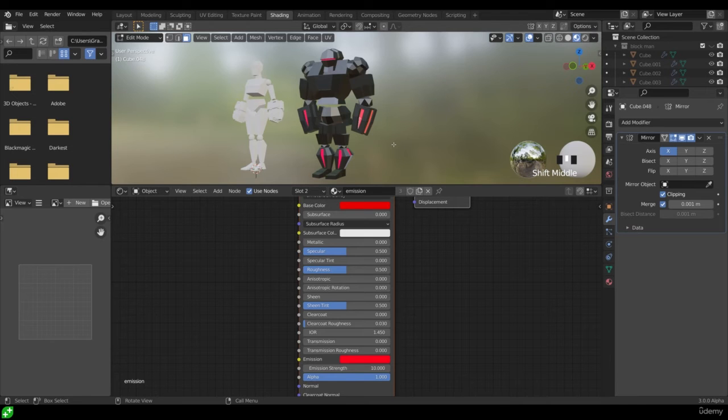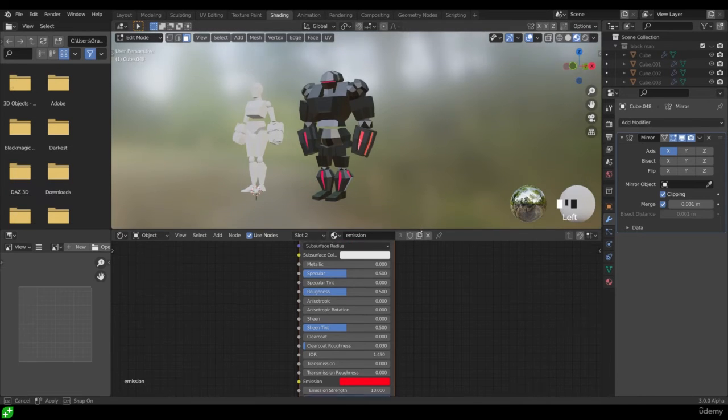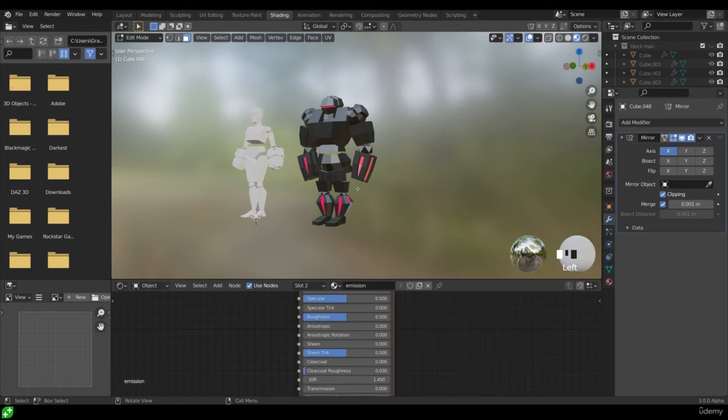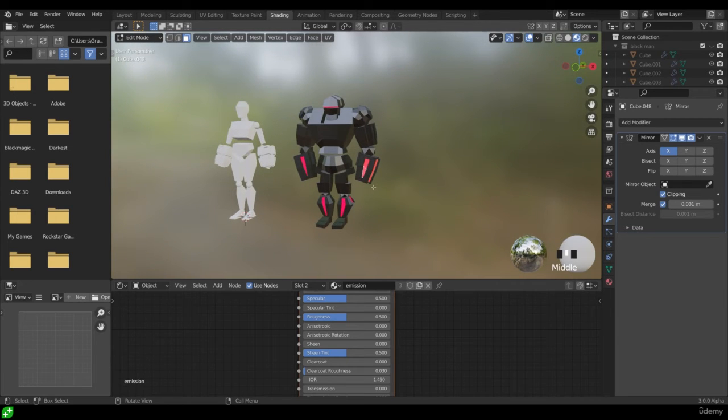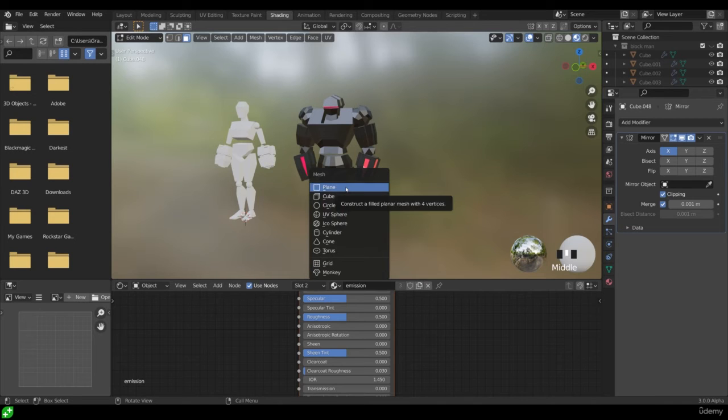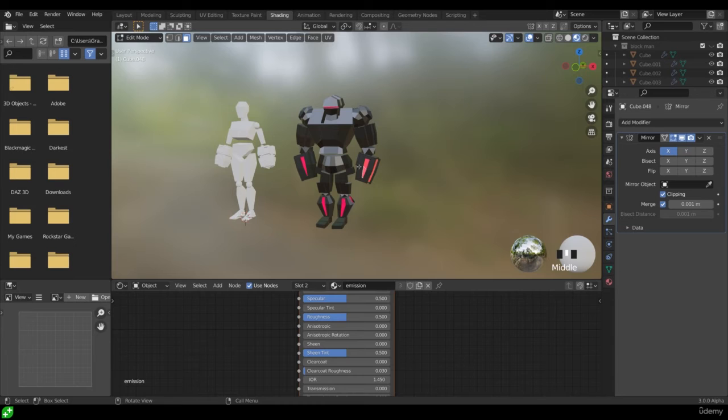Lastly, we want to think about how we can make this look good. Well, let's bring this down for the moment, and I think it would be better if this character was standing on a floor, so Shift A to add. Oh, now I've only got the mesh menu here. Have a think what that means. Well, that means that I'm in edit mode for this object. Remember, when you're adding new objects, tab back into object mode.